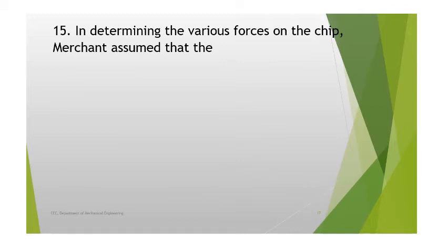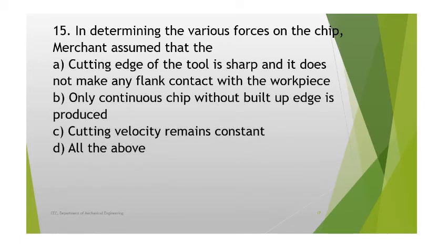In determining the various forces on the chip, Merchant assumed that the cutting edge of the tool is sharp and does not make any flank contact with the workpiece; only a continuous chip without built-up edge is produced; and the cutting velocity remains constant. So the right answer is all of the above.